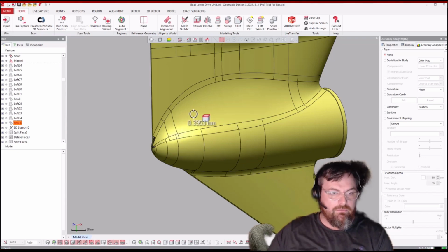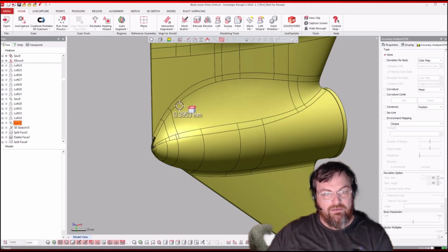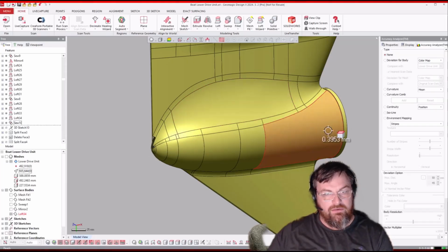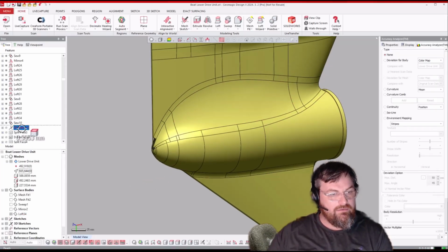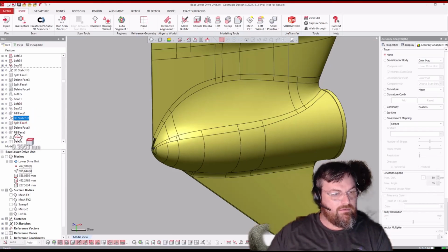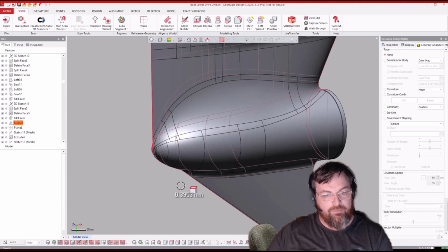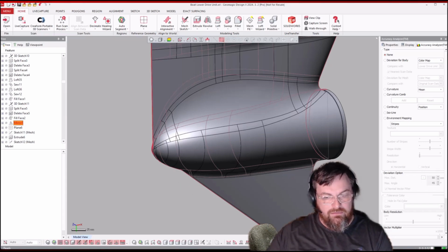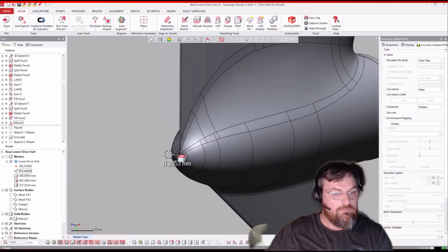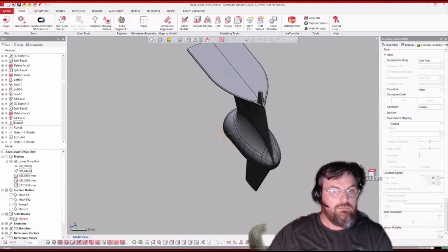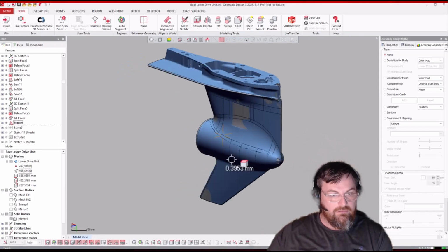But you see, that was just a really neat way of creating that surface by fitting these surfaces and trimming them together. There's a little bit more dress up work down here where we loft, sew, fill face. I'll just skip forward because there's a lot of that. There we go. So once we've filled all those surfaces and buttoned everything up, you'll see that now we end up with a solid. Beautiful. And then turn on the scan. So you see there's our.